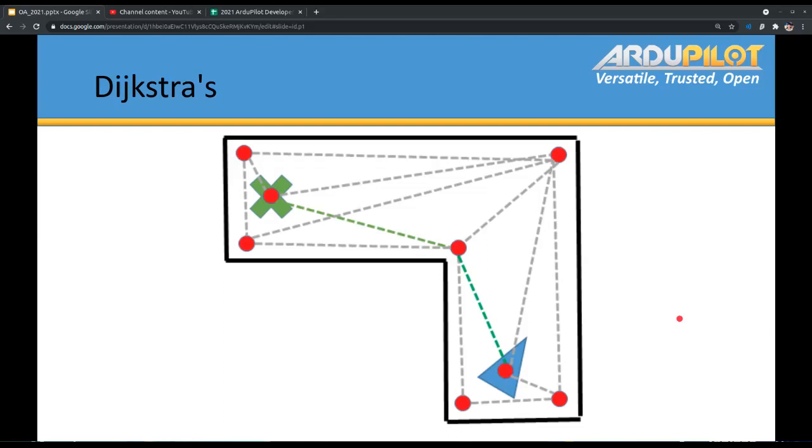But with a low-powered companion board like the Jetson Nano, with anything more than 2 cameras, you're going to reach the CPU limits, and you're also going to reach the bandwidth limit of the USB ports. So anything more than two or three cameras on the Jetson Nano is not advisable at the moment.